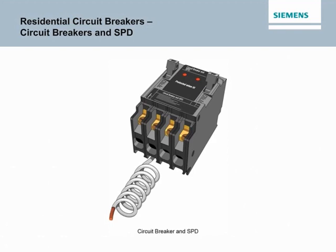Siemens offers a variety of devices intended to minimize damage from electrical surges. One of these devices, the Siemens Circuit Breaker and SPD surge protection device, incorporates two independent single pole 15 or 20 amp circuit breakers and provides surge protection for all branch circuits.